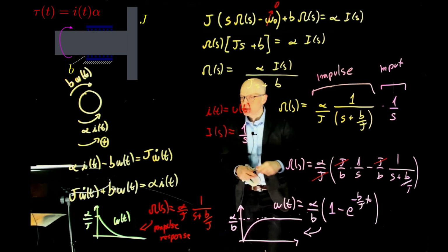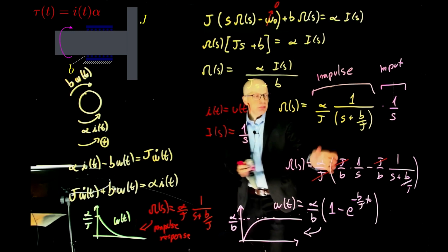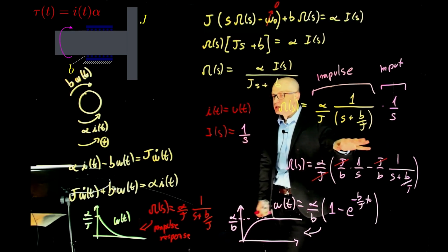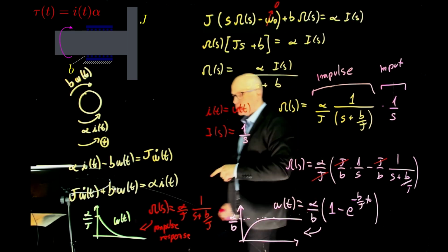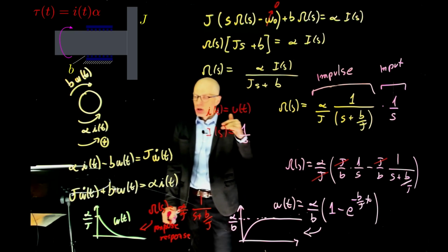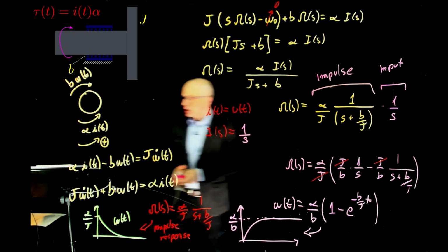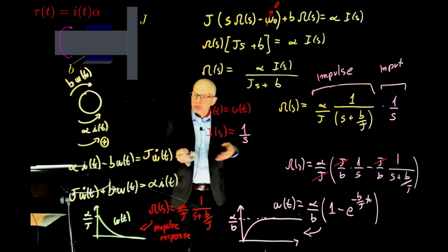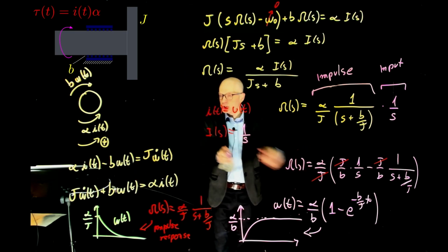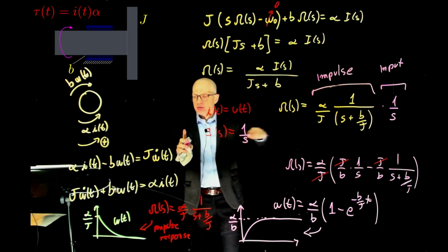And in the last example, the Laplace transform of the convolution of the two signals was simply their multiplication. So what we did here was exactly what we did in the last example. That exponential that was decaying to 0 represented the impulse response of a given system. And then you took the convolution between that function and an arbitrary input, which in that case was just a function that would start at 3, go to 1, and at 5 seconds would turn off.